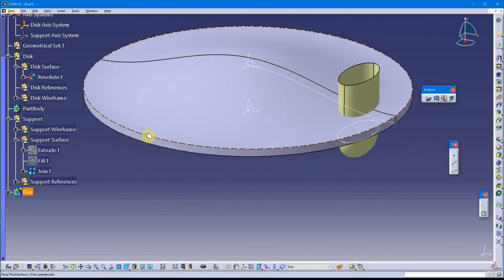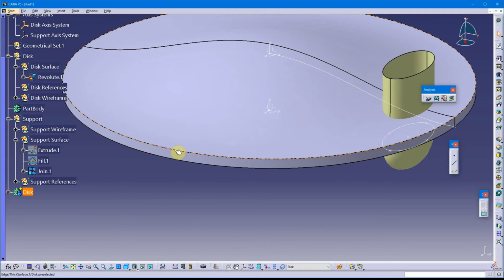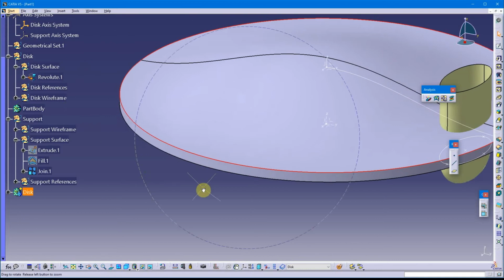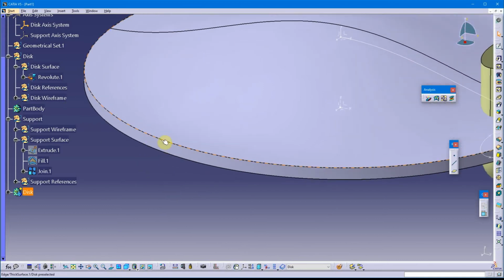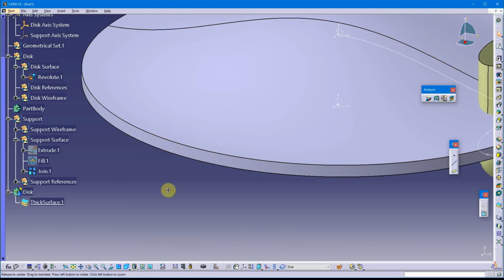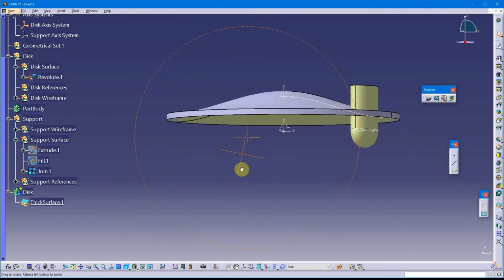And I don't like these. I call these G0 corners. That's a sharp edge, of course. The topological edge. I call them a G0 edge because it has G0 continuity across here. So I'm going to throw in a tritangent fillet there to round that up.